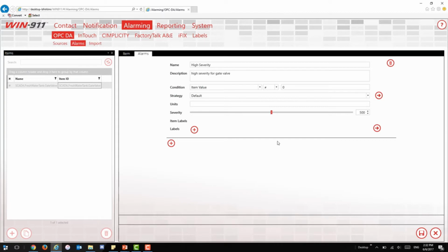And then the severity. So natively, the system does not know what constitutes something high severity or low severity. So we're going to tell it what to look for and tell it that this alarm we consider to be this level of severity. This is useful when you're creating the advanced tactics. That way, if you put in a decision block, check the severity, is it lower or higher than, let's say, 400 or 500, whatever it is, it's going to refer to this and say, okay, well, this has been assigned a severity of 500. It is higher than 5 or higher than whatever we're checking for. So we're going to go ahead and do X or do Y based on the severity that the user has set up and assigned to this particular alarm.